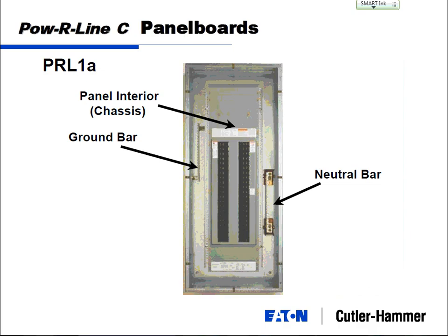And we talked about the ground bar. Here's actually how we do this. You've got the can, you've got the interior that mounts right on there. We'll provide a ground bar for one gutter and a neutral bar for the other gutter. Ground bars normally bolt right onto the can, metal to metal. So your equipment ground bar will be part of your can as well.